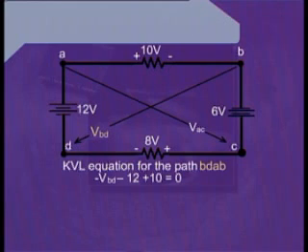As we reach at the point D, we will be looking towards the point A because we are following the alternative mesh. Looking towards the point A, we can see that there is once again a voltage source attached between the point A and D, and that voltage source has been marked as having a value of 12 volts.